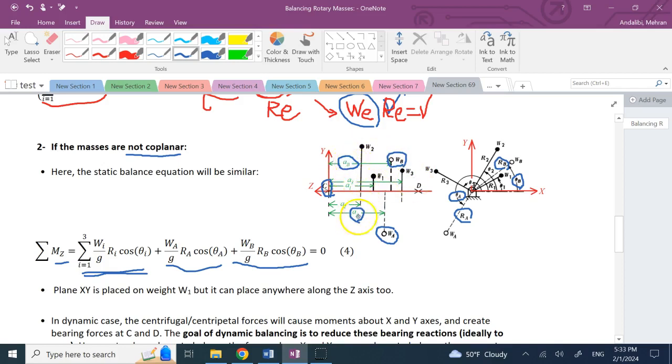And the reason you pick AA and AB as the same as A1, A2, A3, because you want to attach these small masses onto the already existing what? Discs or gears. You don't want to separately add another mass off balance with respect to the shaft.